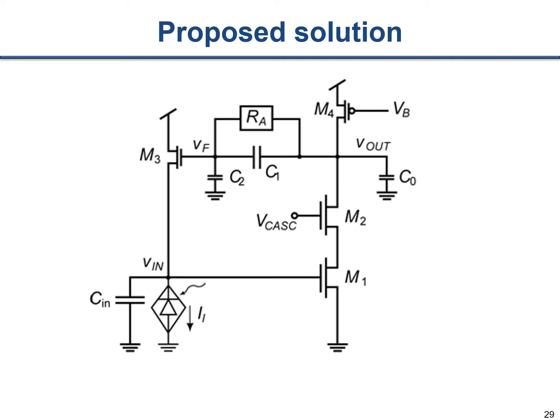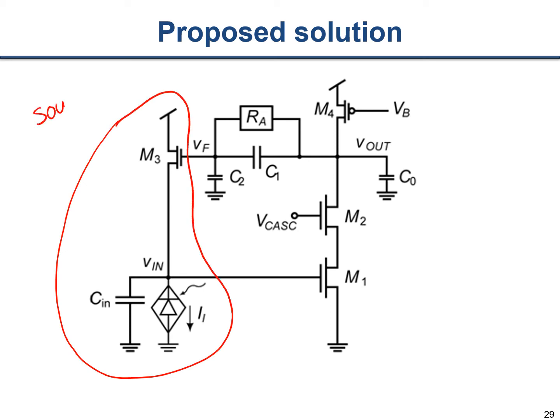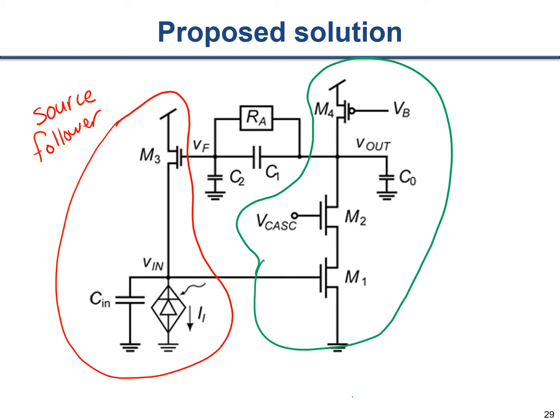So the solution is this feedback circuit. The circuit that we just looked at is right here. We're going to call this the source follower, which includes the photodiode. The output of the source follower, we want to put through a gain circuit. We want to have some gain in our feedback loop. And then we want some sort of feedback circuit that feeds the output of this gain block back to the source follower in order to provide some feedback control of the circuit.